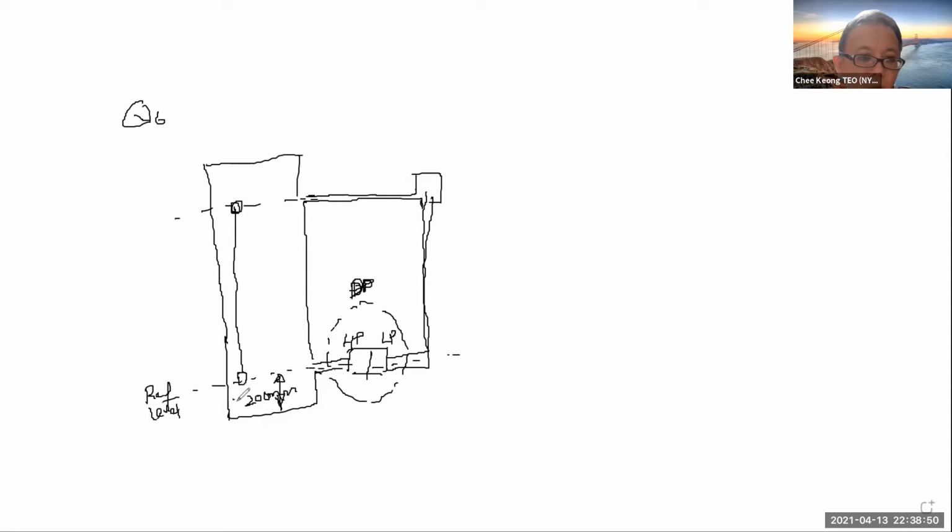200 millimeter actually got no use. And of course, above here, there is 100 millimeter, there is no use. Also, these two are no use. So what is useful is only between this range. Now, all the pressure will be calculated using the head pressure. So pressure for head pressure is given by height times by rho of the liquid times by gravitational pull.